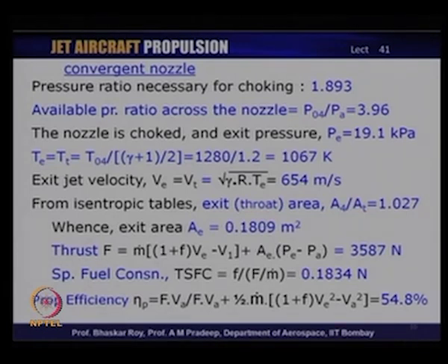The available pressure ratio across the nozzle right now is 3.96 from the computed parameters of this particular engine, and hence we can say that the nozzle is indeed choked, and hence the exit pressure would be as per the critical pressure that is ideally available, and that would be 19.1 kilopascals. Correspondingly, the exit temperature, which would be the same as the throat temperature, the exit being the throat itself, would be 1067 K.